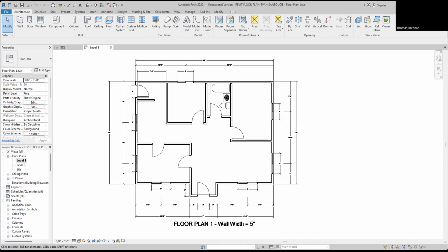Like a 20. A 20, that's right. And what that means is 20 feet are represented as an inch. Okay, so you see an inch, it'll basically represent 20 feet on the plan. There's also 30, 40, 10, a few others right there, but this is what you use for this. Now, whenever you're working with a plan like this, you always look for the scale, and in this particular plan, the scale is right up here. It's actually 1 inch equals 20 feet.